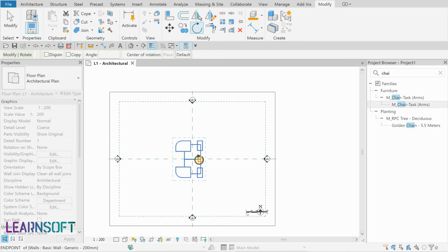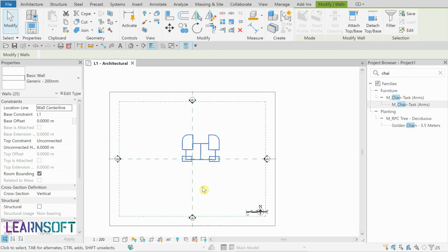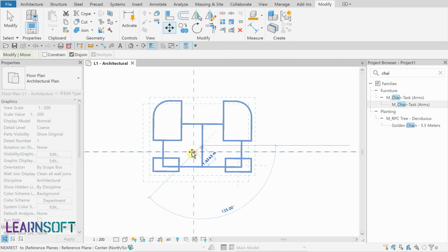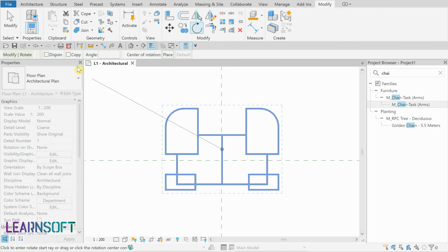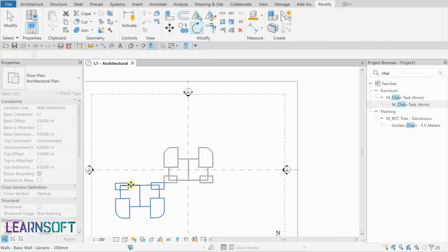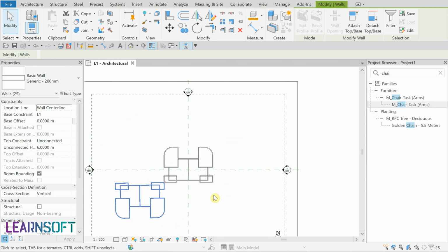Once again, place a new spot for the center. Once again, rotate 90 degrees clockwise. We learned about the copy function in the option bar. Do you know what happens now? Exactly. The primary shape is kept and a second shape is created during rotate.